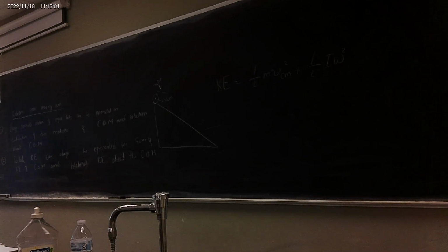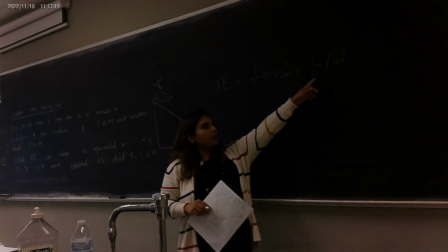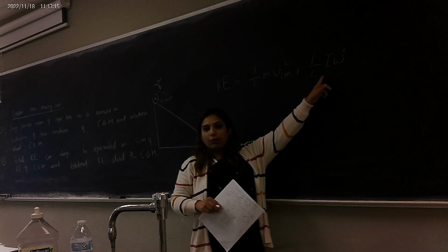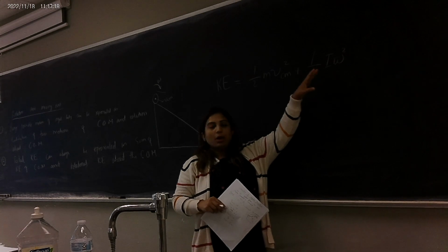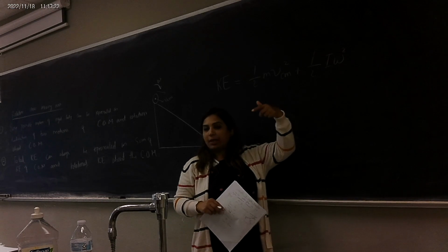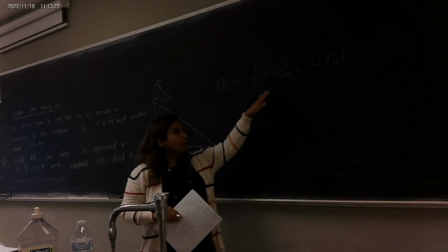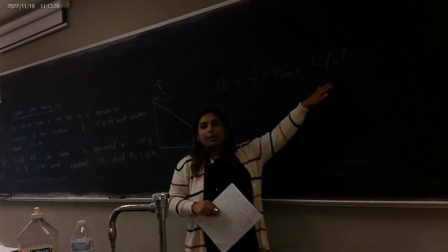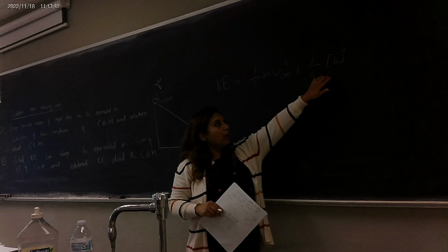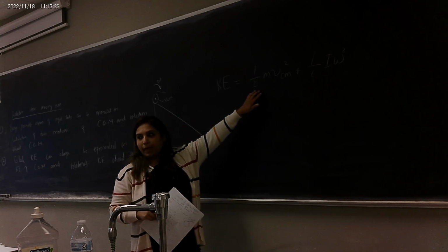Good so far? Does that make sense? Because it's not alone. This time, it's not just rotational, like we saw in one of the problems where the pulley was fixed and you are pulling the string out of it, and it's rotating. There would be some situations like that. In that case, you just have the rotational. But if it is translating and rotating, then you have to figure out the kinetic energy about the center of mass plus the kinetic energy on the straight line.